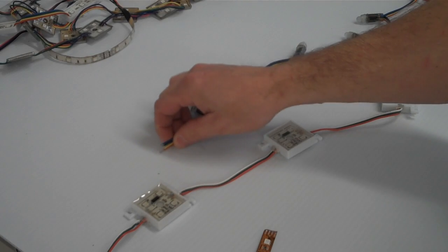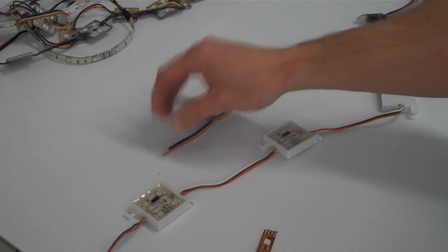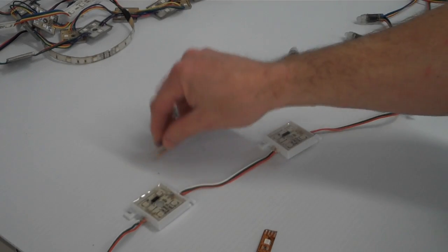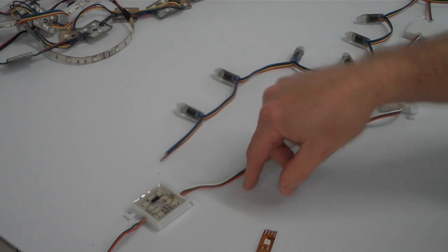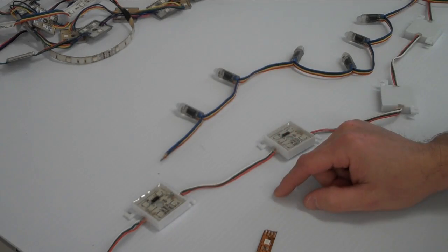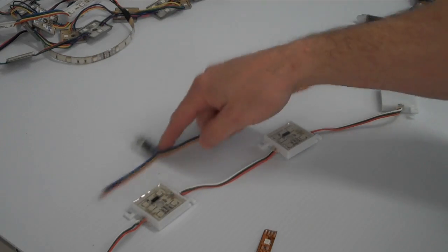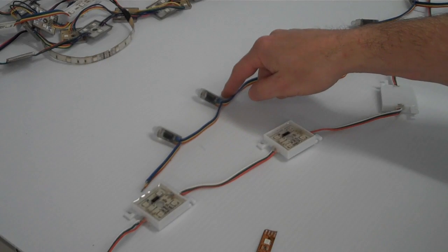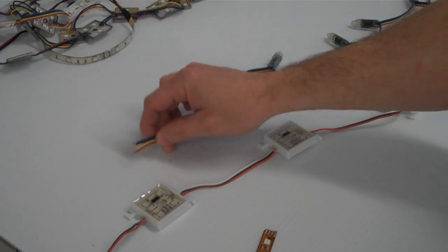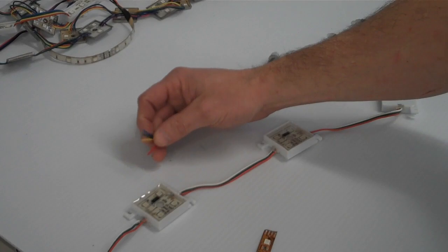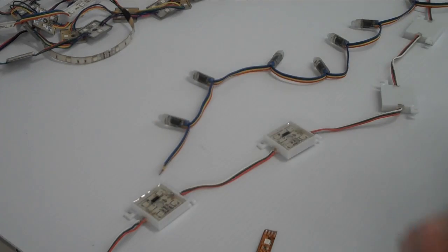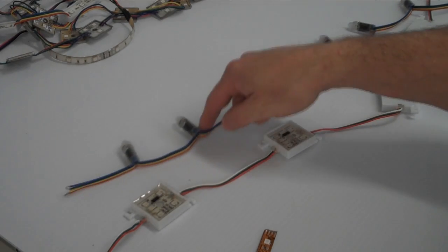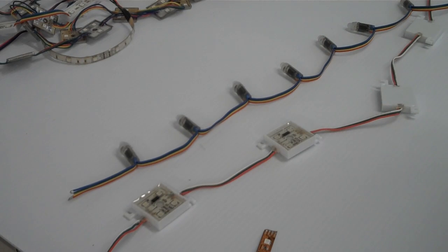Within your controller, you can set up a phantom channel that says, okay, channel number 1 is red, channel number 2 is green, and channel number 3 is blue. And it will actually tell each one of these, even though they're individually addressable, to turn on to a particular color. What this does, of course, allows you to only use 3 channels, which is great if you have software that is limited or you have a problem with outputting huge amounts of data that is required, and we will talk about that later, to the pixels.